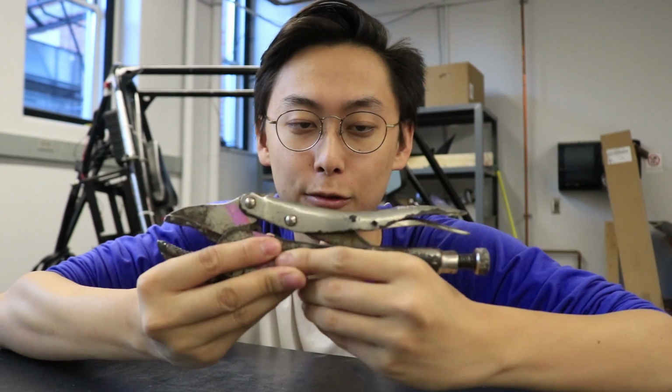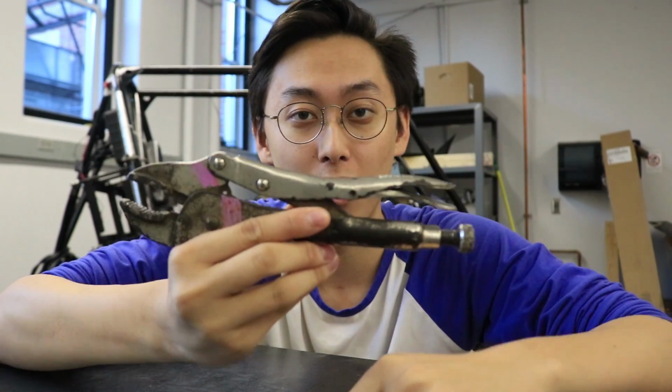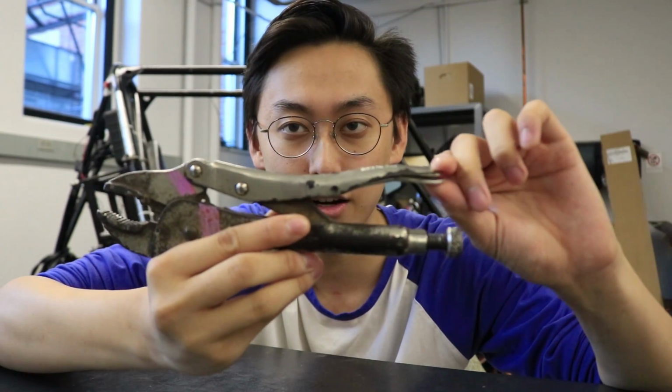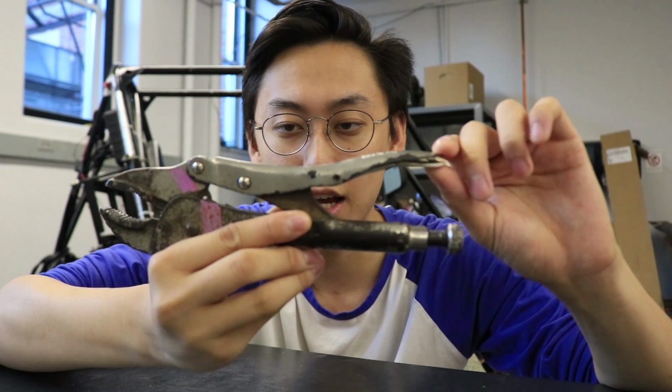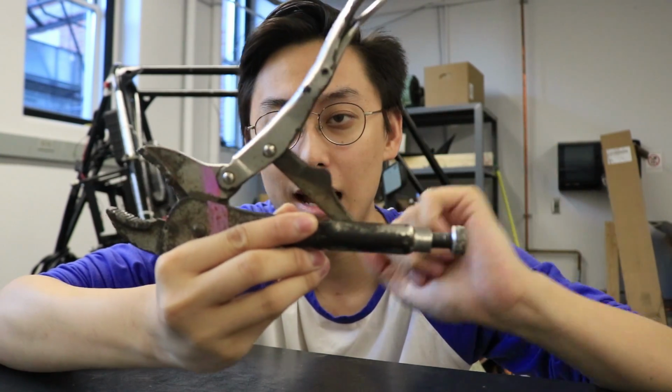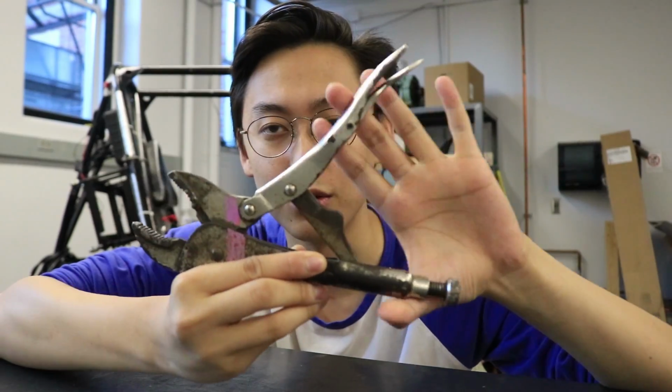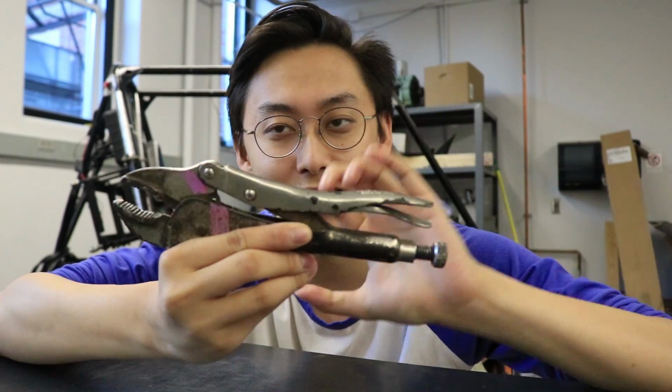Now, we can force this 4-bar out of the toggle position by pressing here and leveraging it right outside of the toggle position. It will snap out because there's a spring right in here that allows it to do that. And that's how we want to do our toggling, because that's exactly the kind of motion we're looking for in our steering, and those are the basic ideas of that.